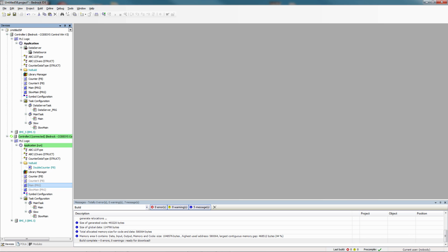Once the problem does occur, a preset amount of data can be stored before and after the trigger event. The IDE does not need to be logged in for the DSO to run. The HMI can be configured to indicate when a trigger has occurred and page you or send you a text message. Then you can log in at your IDE and look at the data before and after the event to help you diagnose why that event occurred. So we'll demonstrate this quickly.